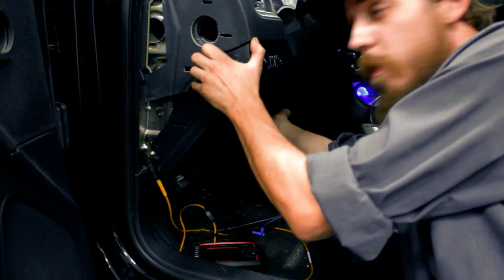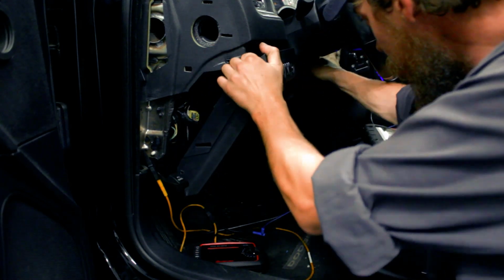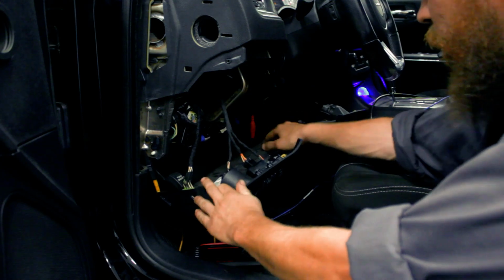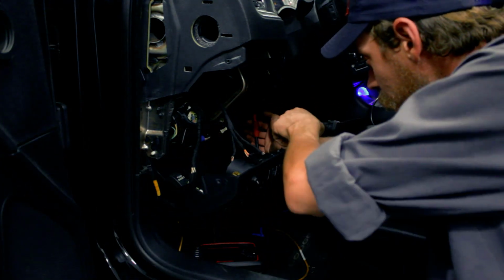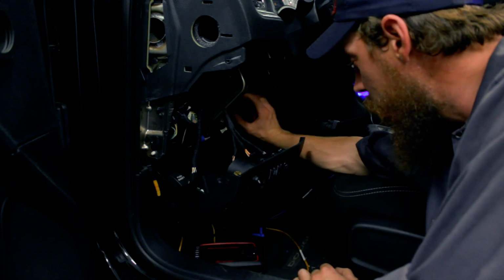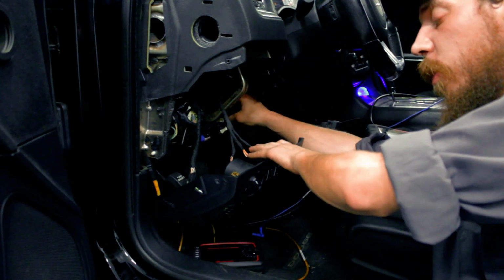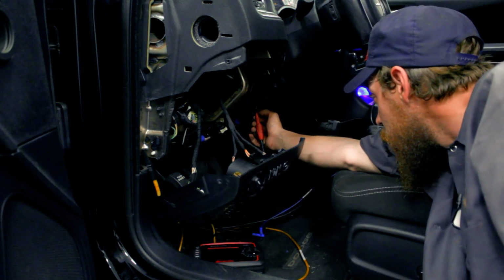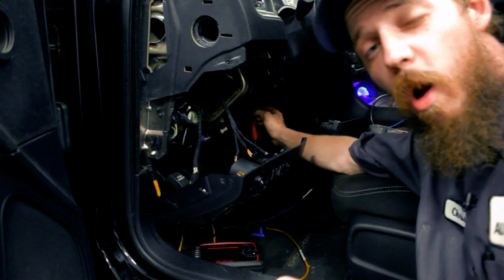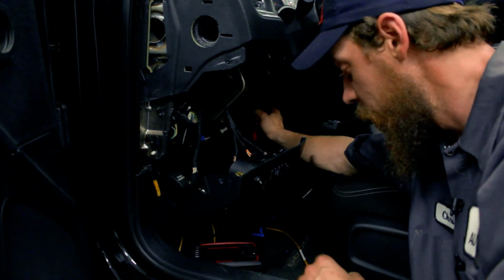So that's what we're going to do. The instrument, or lower dash panel here, I've already got the screws out. I've already got this set up. And what we have back here is I am actually back probed. The TCM is located directly under the steering column below this lower dash panel. And I am actually probed into a dark green orange wire, which is our transmission temperature sensor.